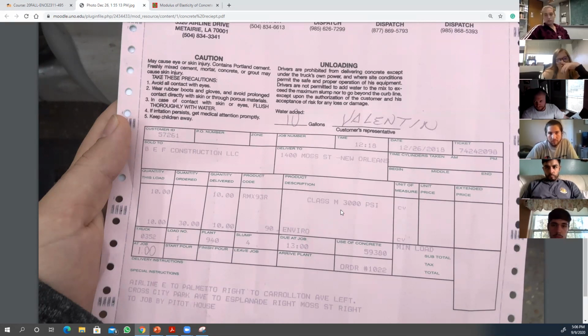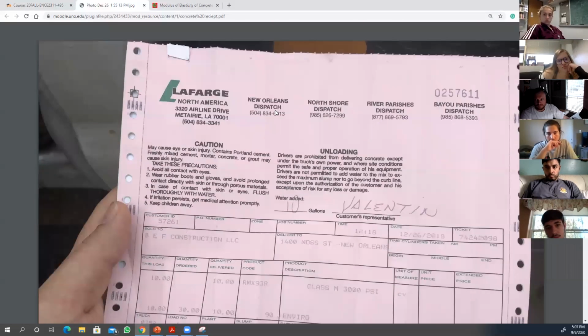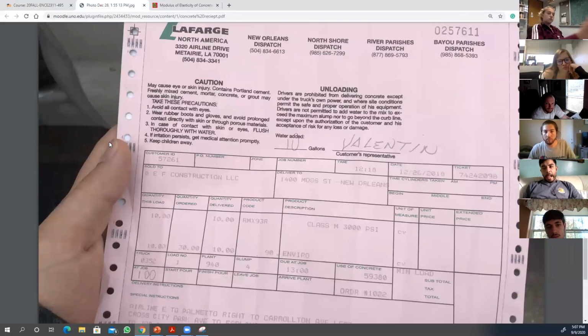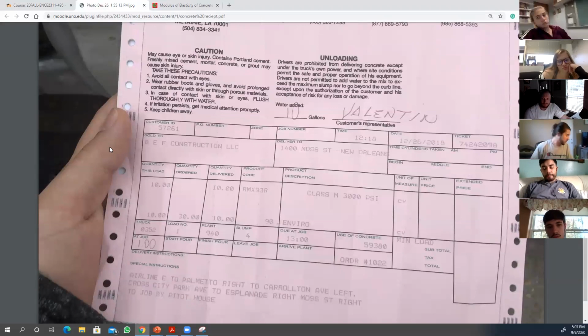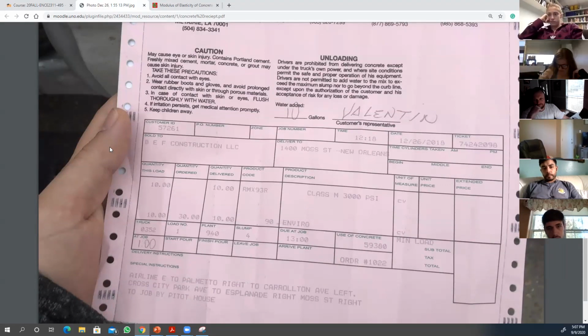You assume that it's going to rip it up, exactly. You're going to do demolition, take out the bad concrete, and then pour another one. Who's responsible? Not you, this company, Lafarge, or any other company. I'm not affiliated with this company, but it can be any other company. So your job is to check these. And you should understand by now why this is important, why I'm trying to explain the slump over and over, or the concrete compressive strength, because this is what you're going to see in the field.